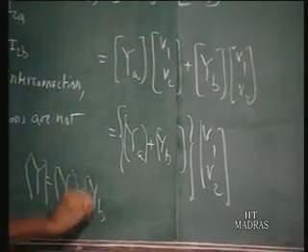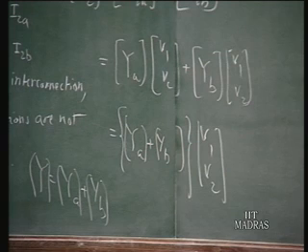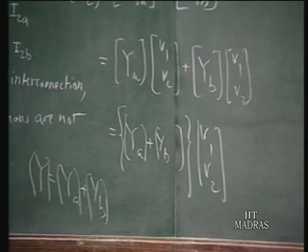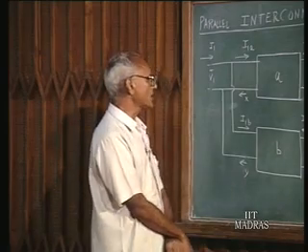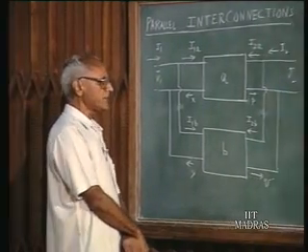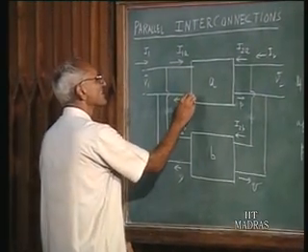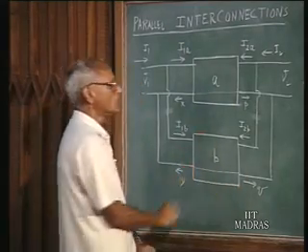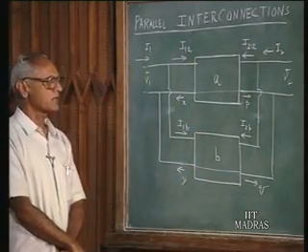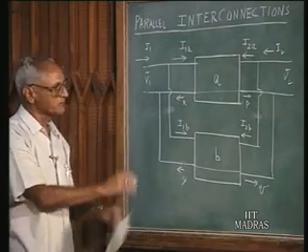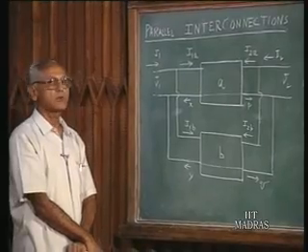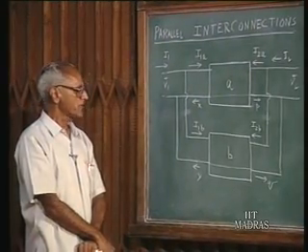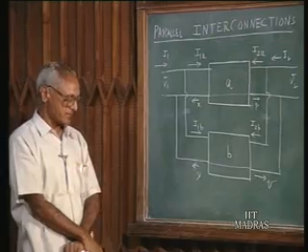That means when you have two two-port networks in parallel, Y equals YA plus YB, as long as the port condition is not violated. And you can take it for granted that as long as we have 3 terminal 2 port networks, that means there is a common lead going through, the port condition is never violated and this particular rule will always be valid. In other cases, you must make special tests to see that the port conditions are not violated.